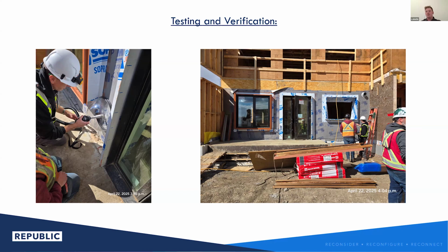And I can't state how much value clients get from partaking in this process, because for every dollar spent, you're saving so many dollars in terms of future maintenance hassles. Through air tightness testing, you're minimizing any potential leakage points, both moisture or air, within the building that are really going to lead to future issues.